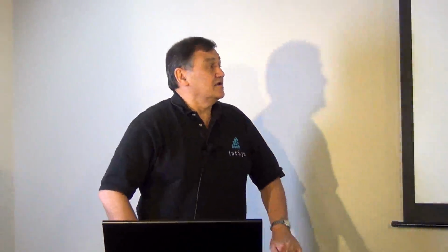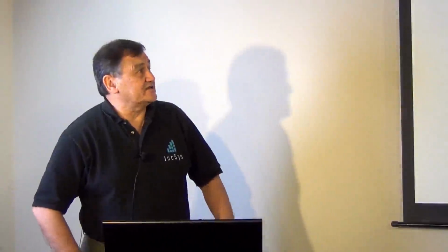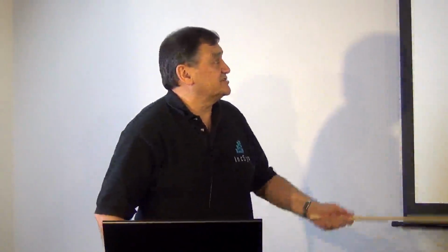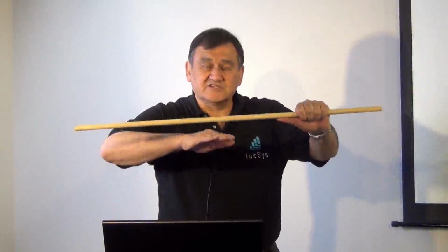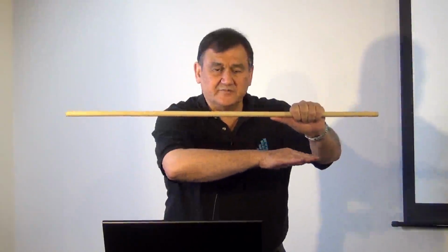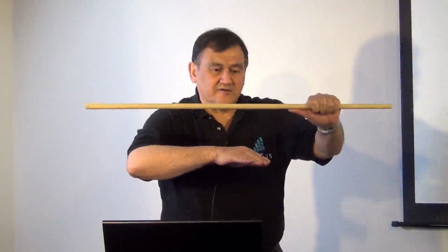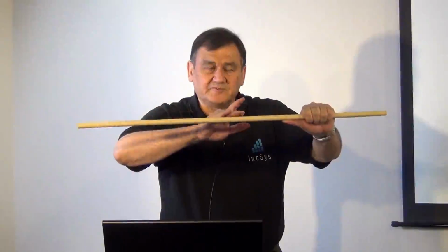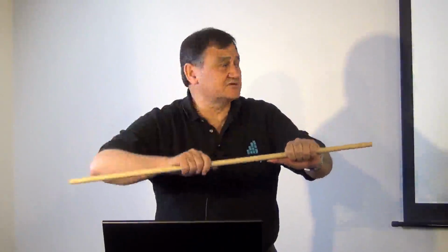All right, so looking at a little more detail at a simplified diagram for a transmission line. Basically, there's a reactance effect because, like we said, those conductors have magnetic fields, and we represent that as a series reactor. Those conductors have a capacitance effect. The conductors are in parallel, and based upon the conductors being closer and closer to each other, you can have a buildup of electrons on one versus the other. Again, all this is happening at 60 cycles per second.